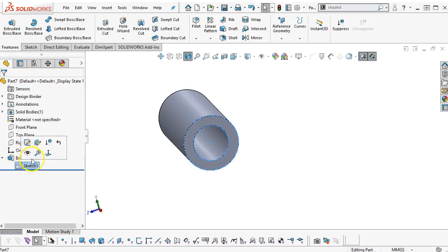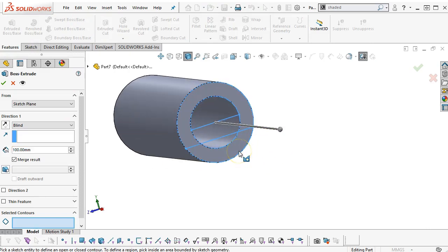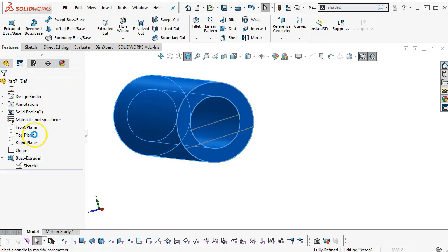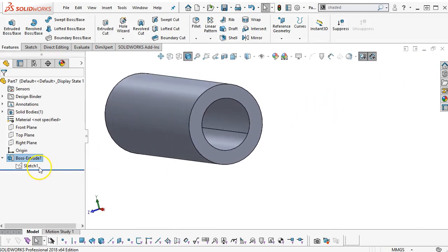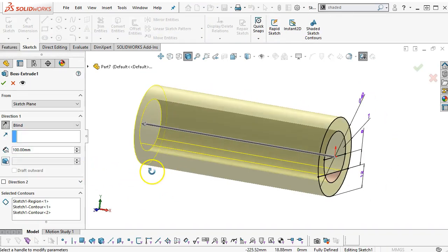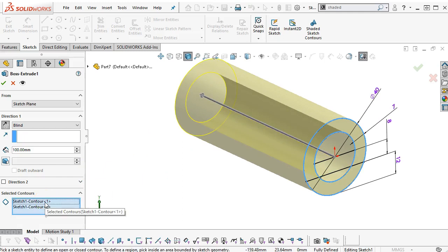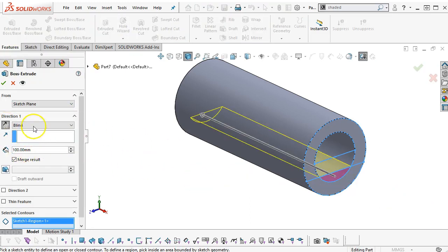So sharing the sketch, highlight. We're going to go with the extrude boss base. Let's see, well, let's go with the two regions. And actually, let's go back into the definition of this and see if I can pick up that region, because that goes all the way through. So I included it, but it doesn't look like it really did anything adding to the geometry with that extra. Okay, so that being the case, we'll extrude that all the way through. So that geometry reverse through all.